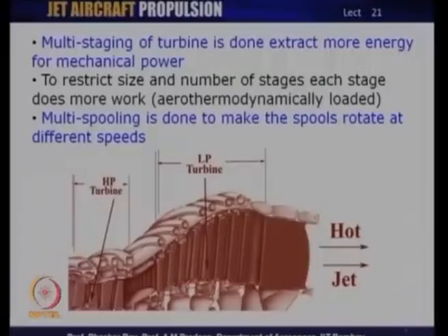If you keep on increasing the number of stages, the total amount of space that needs to be allotted to the turbines would go up, the length of the engine would go up, the weight of the engine would go up, and many of these things are not really acceptable to an aircraft application or to an aircraft designer, really speaking. And as a result, such turbines and such engines are unlikely to be accepted for aircraft applications.